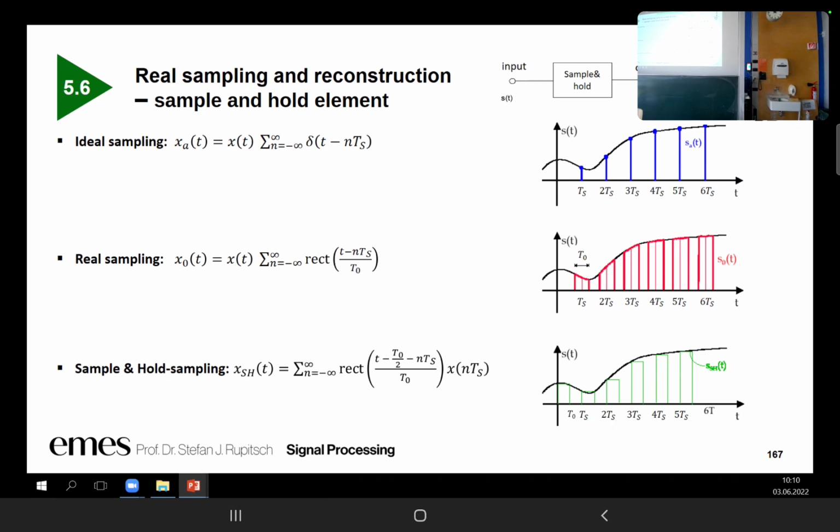Conversion always takes time. Yeah? You cannot convert a signal immediately from the analog world to the digital world. The signal has to remain constant for a certain instant of time because the analog-to-digital conversion requires the signal for a certain instant. We need a certain period because only this way we are able to convert the signal. If it's available only for one instant, and then it's gone, then we are not able to convert it. It should remain constant for a certain period of time. That is the period here. So, it should be constant.